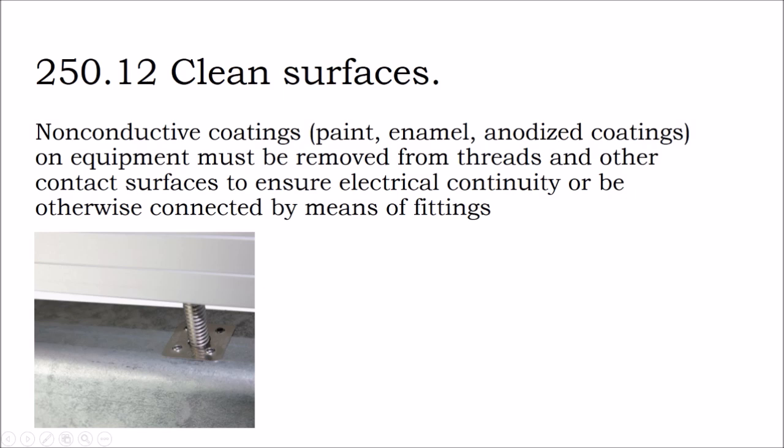And the rack will often be a listed assembly that's listed as a ground path. And so you simply connect your ground to the racking. The racking is listed as an assembly, as a ground path, and then use grounding washers to ground the metal module frames to the railing itself. But on top of that, you'll find brand new components being manufactured, and maybe to keep the threads nice, they put a little enamel coating on them, or it comes off the manufacturing process for whatever reason.